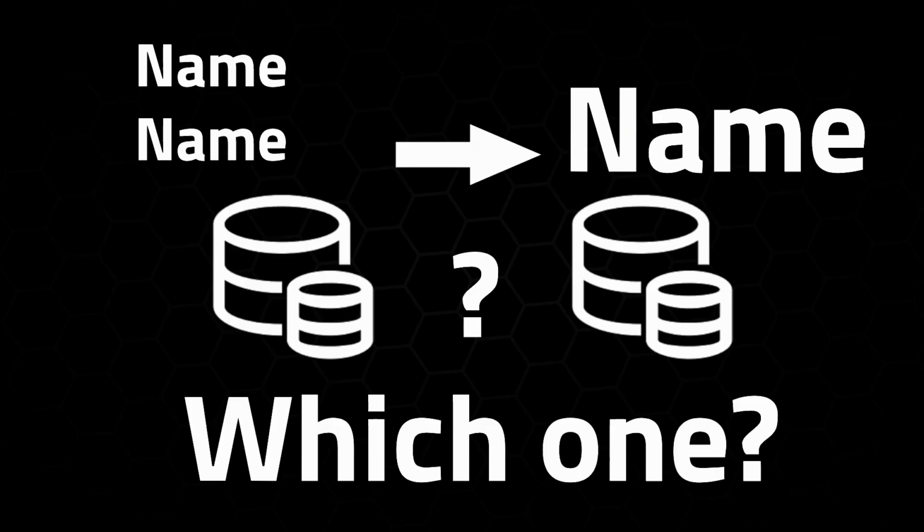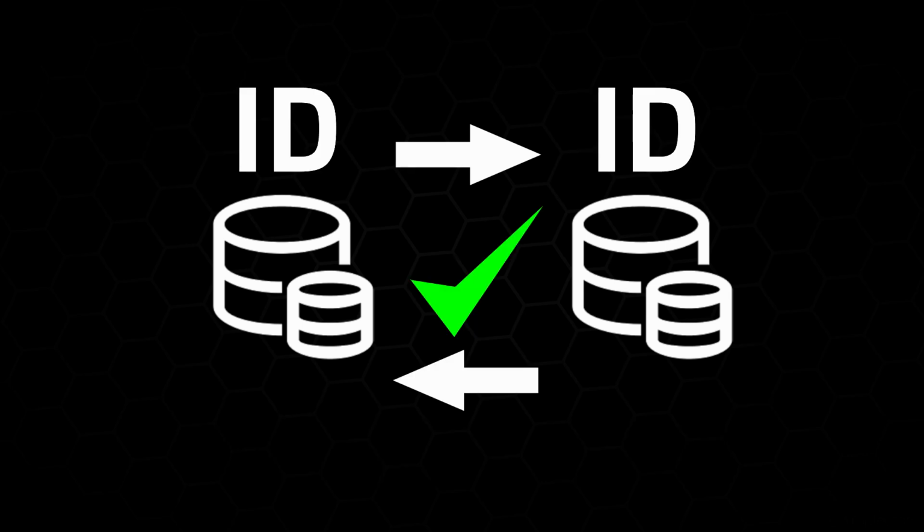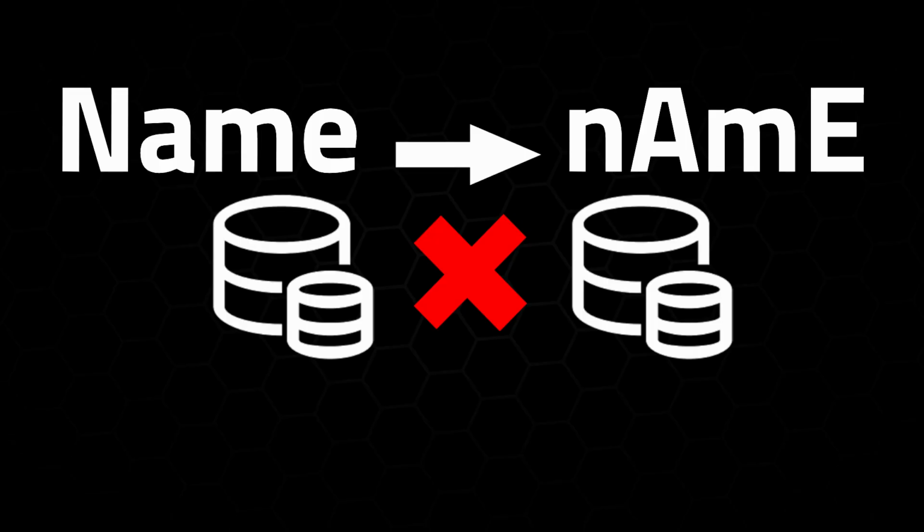We might not be able to use some fields that you might think are unique. For example, a room name you might think is unique, but as you know in Revit, you can have rooms with the same name. So we can't actually match these elements when we come back to Revit based on their name, for example. So we use an ID as well because the user can't modify this property. If people go and rename things in the middle of an export and an import process, it's going to mess things up if you rely on that when you return back to the model, or a number. But an element ID, a user can't change.